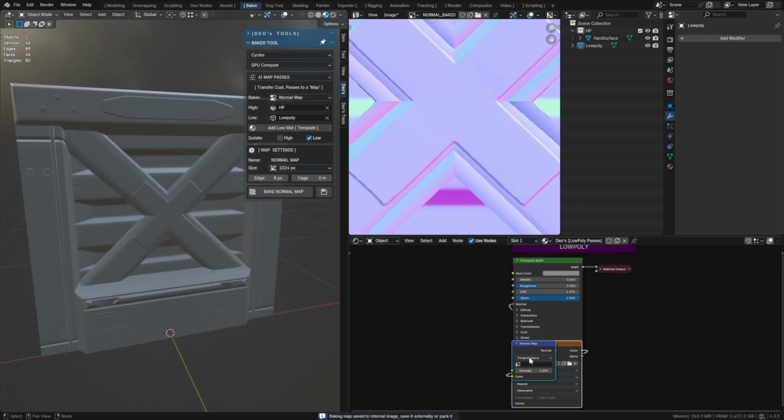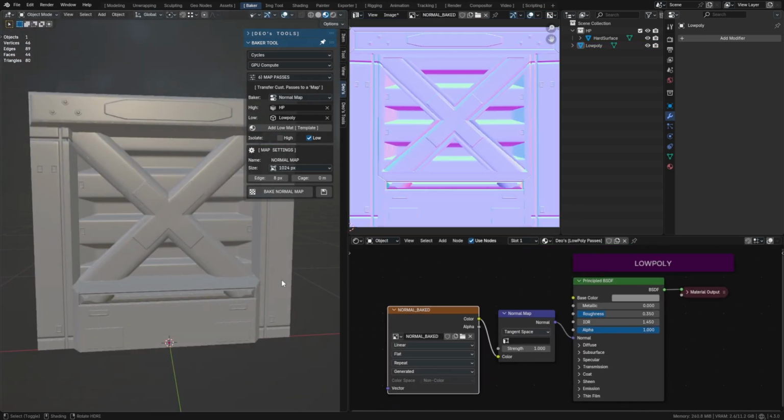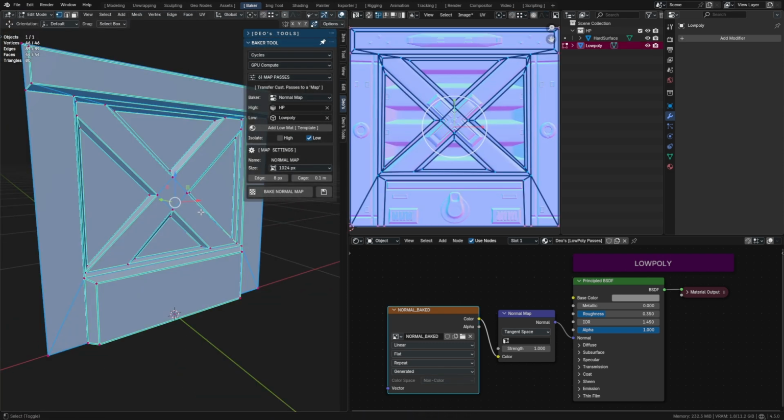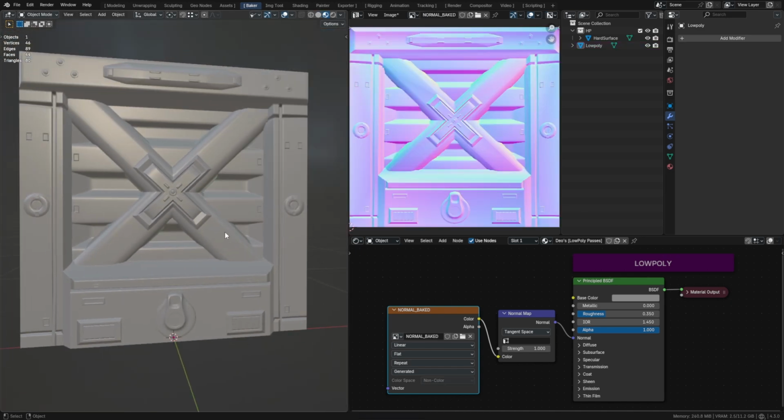This will create the needed nodes to view the normal map. Modify the cage value as you need, and also use Shaded Smooth to calculate a proper normal map and see the result.